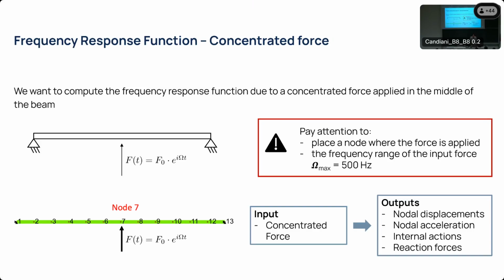Okay, if not, remember that sometimes we are not interested in finding the free response of a structure, which is the one we already know how to compute, but we want to see what is the output response of a structure based on an input that we decide to give to it, which can be, for example, a harmonic load, maybe the movement of a piece of machinery, can be the wind, can be any possible external load or movement of a constraint which is applied to our structure.